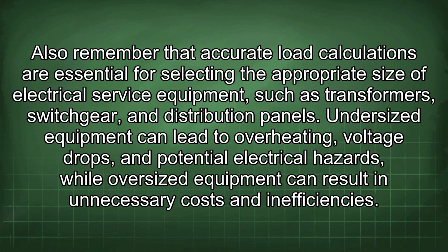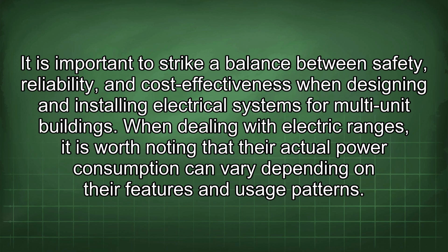Also remember that accurate load calculations are essential for selecting the appropriate size of electrical service equipment, such as transformers, switchgear, and distribution panels. Undersized equipment can lead to overheating, voltage drops, and potential electrical hazards, while oversized equipment can result in unnecessary costs and inefficiencies. It is important to strike a balance between safety, reliability, and cost-effectiveness when designing and installing electrical systems for multi-unit buildings.